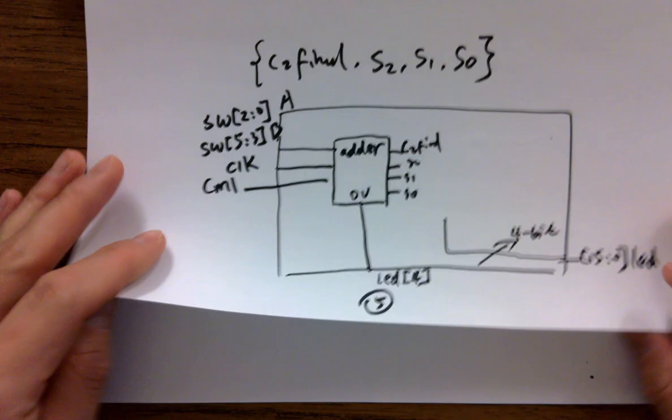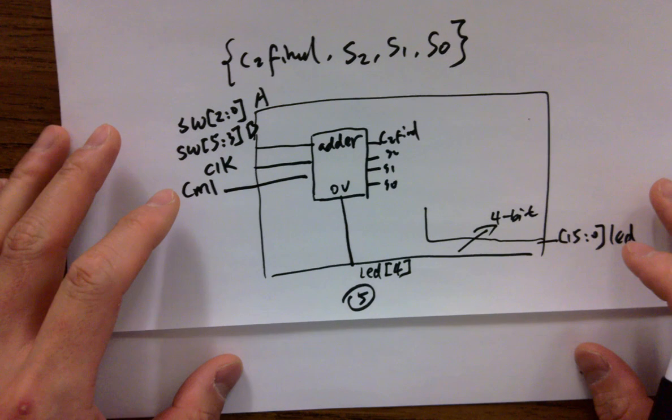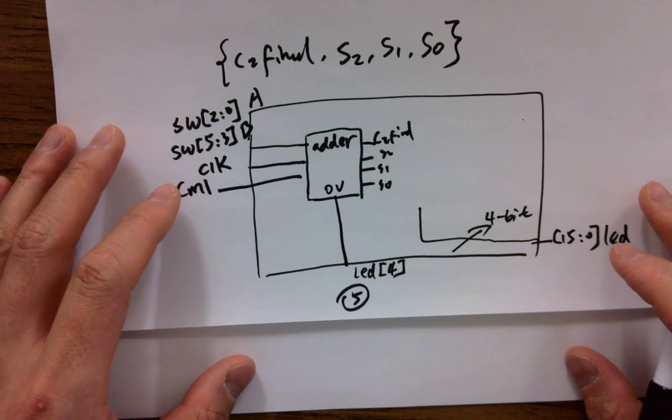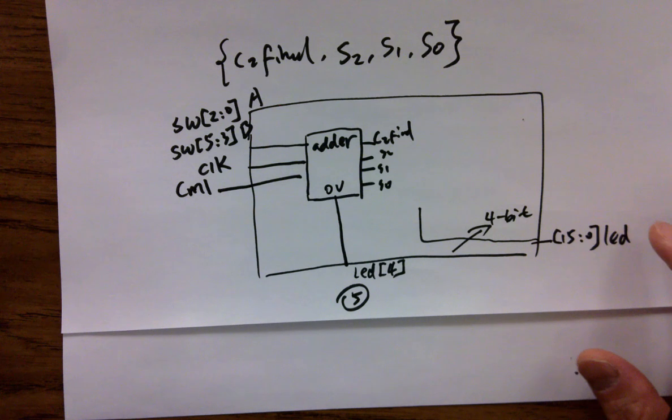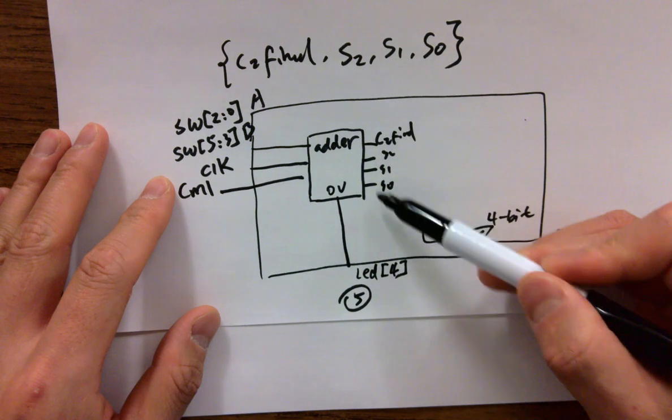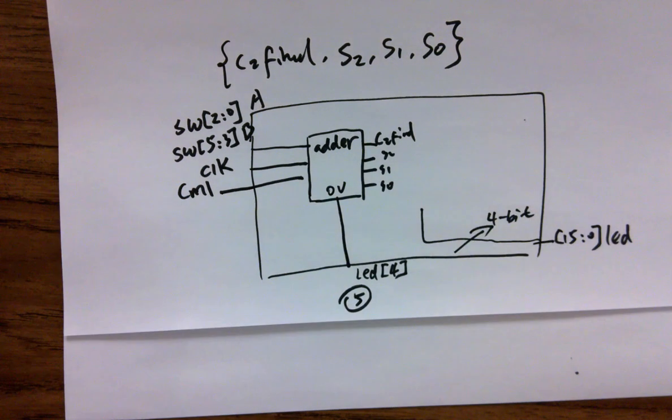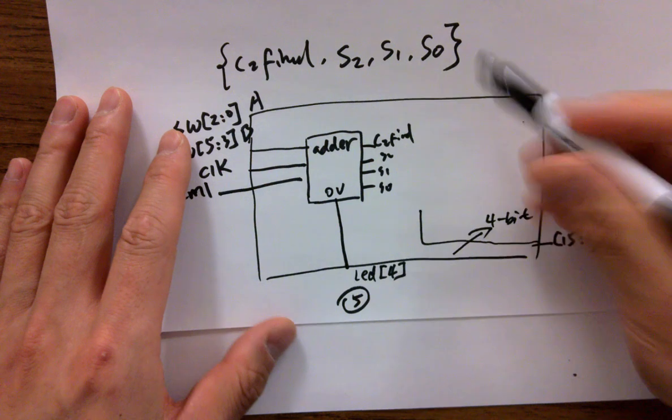Okay, so what are the goals? I want to display the number on a 7-segment display, because a lot of people cannot read binary numbers. Is that easy to do or not? It's like a digit of the previous lab, right? It's a 4-bit input as a digit of the decoder. So you need a decoder here, right?